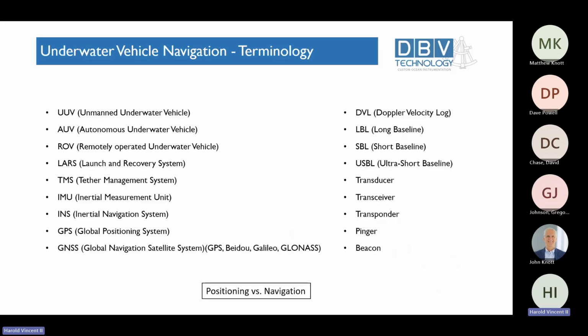And so if we compare that to, say, a drone in the air, the reason we need to have that wire underwater is because we do not have the same advantage of radio links. Radio control or remote control cannot generally be done wirelessly underwater using underwater acoustics because there's not enough bandwidth and there's too much latency. So if you want to have a human controlling the underwater vehicle, you have this tether or wire or cable between the two.